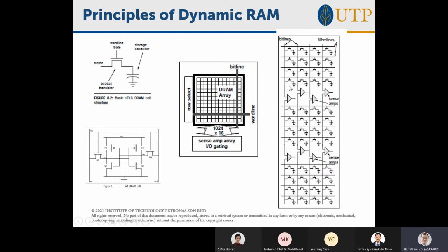If you're a little bit sharp, you'll ask: you're reading this out, so the charge is going to discharge out and raise this bit line. But once the charge comes out, this bit line goes up. Didn't I just use up the charge in the bit? But I'm supposed to store the value in the bit. You'd be right. Reading out from a DRAM is actually a destructive process.